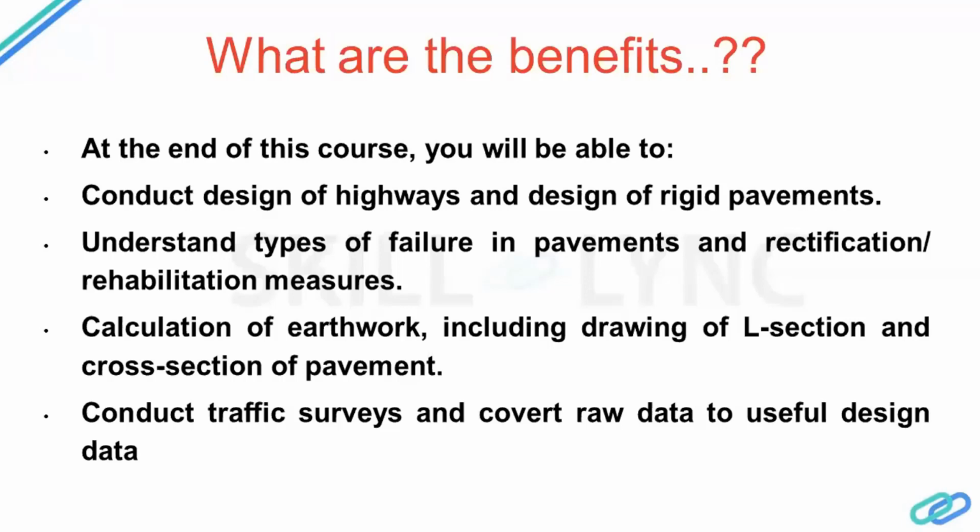How the design of highways goes into, like, what is the number of lanes that you need to keep, what is the lane width that you need to maintain, whether you need to provide a median on that specific pavement or not, and what should be the width of that, what should be the length of acceleration and deceleration lanes, what should be the curve of the radii. So these all are influenced by the traffic surveys, what kind of traffic you have.